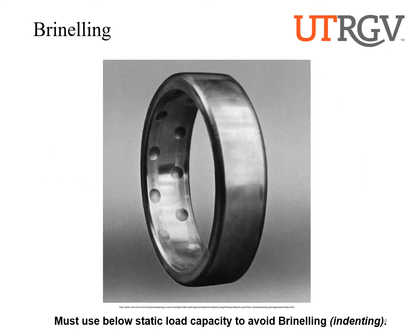We talked about Brinelling, right? And we said, look, if you exceed the static capacity of the bearing, what's going to happen is that those rolling elements are going to cause high enough contact pressures, and remember the associated shear stresses, that they can lead to permanent deformation of the bearing.